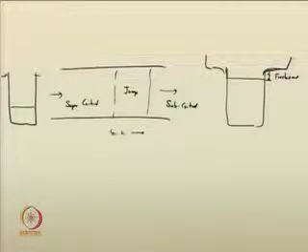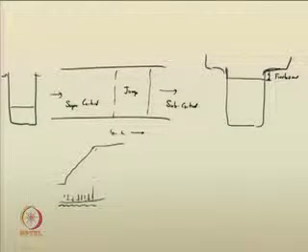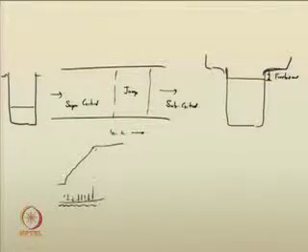Not only that, the profile will also help. Say if you have a profile like this in the channel bed, with respect to the water depth, the pressure will be exerted by the water on the channel bed. So, based on the profile, you will be able to evaluate the pressure force, and that pressure force will be used in the structural design or the material design of the channel beds and all, both for the sides of the channel as well as the channel bottom.